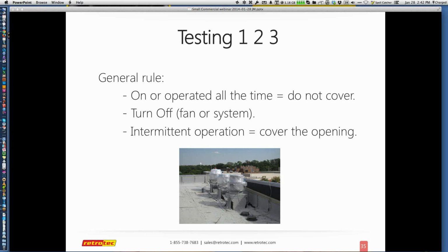So one of the questions I got a few seconds ago was about drop ceilings and air barrier. In general, it's a misperception that the drop ceiling would be thought of as an air barrier, even though they do put insulation on drop ceilings, which almost makes it ineffective. So if you're really trying to determine the volume, it should be what's above the drop ceiling. Maybe you have a drywall ceiling and it's still an additional roof, but in general, the roof is your actual air barrier for many of these cases, and that's where the insulation belongs. If it's not, you're going to find that they've really challenged where the air barrier is and the thermal envelope, and they really should be in line with each other.